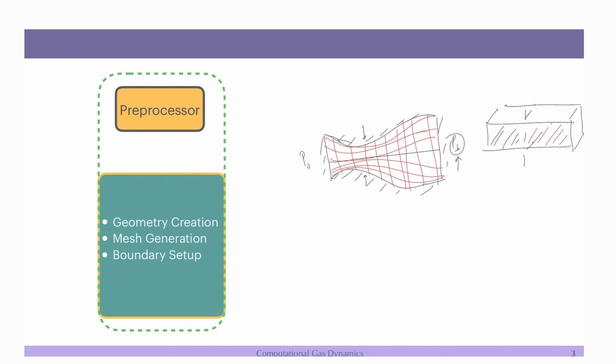Even if you want to use OpenFOAM or any other solver for high dimensional, complex problems, that is fine, but the steps that we have, for example, how to make a grid, how to distribute the points, how to reconstruct, how to calculate the flux at the interface, how to time march it, how to apply the boundary conditions, everything will become clear to you when you write a 1D problem and solve simple problems like the shock tube.